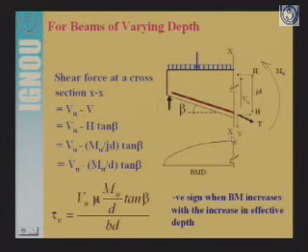Minus for this particular situation that we see here, for a case when the bending moment is increasing along the section when the depth is also increasing. Means in this case, when depth of the beam is increasing as well as the bending moment is also increasing in that direction, we will take the minus sign in this expression.